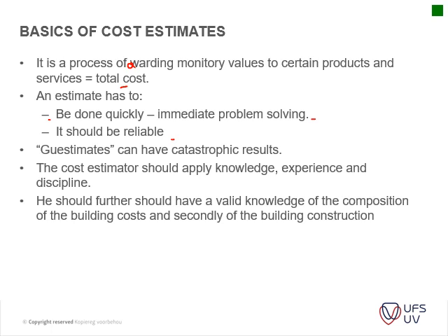He has to know what the influence of one professional is on the other. So for instance, like I just mentioned, if the structural engineer changes something on this side, it may influence the look and feel of the architectural side as well. Where will the electrical ducting go? Will it fit within this flat roof design? Is there enough space? Air conditioning ducting is usually a big challenge. Do the services clash with each other? Those are the things that he has to look at.